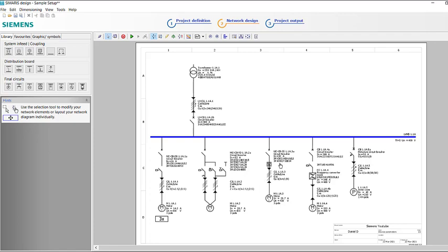We've got our soft start selected with the protective device. And again, we've got our drive selected with its protective device. In this instance, it's selected a G120. Here we've got our miniature circuit breaker protecting the single phase and neutral load. I'm happy with all of these devices, but what other information?